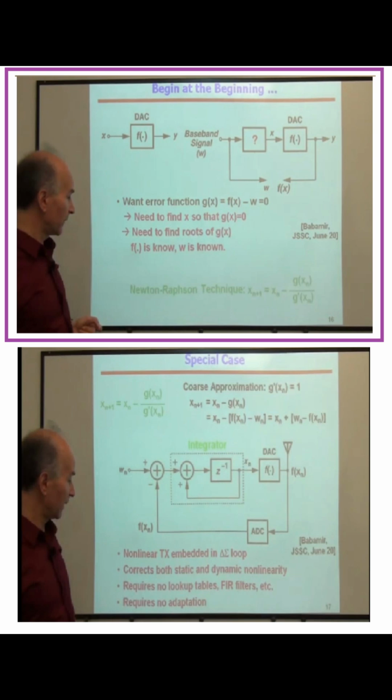We begin with a simple scenario. Our digital-to-analog converter has an input-output characteristic denoted by function f. We assume a static nonlinearity, modeled as a polynomial, creating a nonlinear relationship between x and y. To counteract this, we consider predistortion. However, predistortion does not support real-time or background correction.